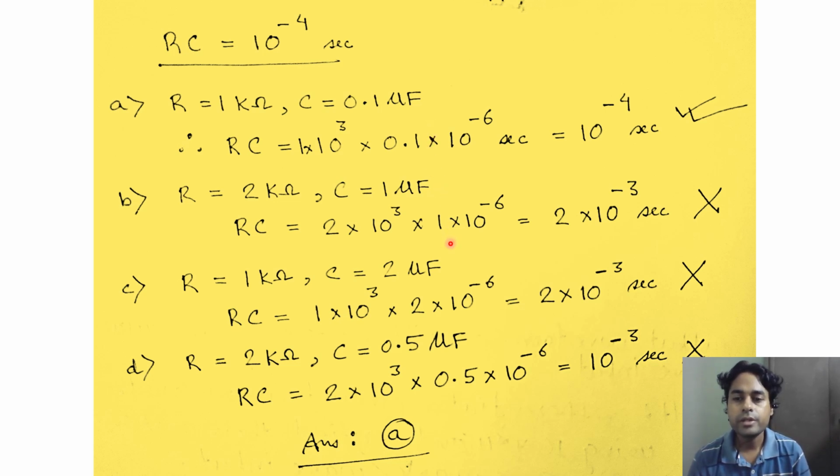So this was a pretty simple problem and it could be remembered. You do not even have to go through obtaining that voltage divider equation. If an RC circuit is given, then simply remember that the cutoff frequency is equal to 1 by RC.